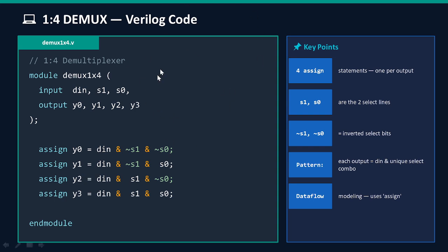After that we are going to write Verilog code. Just like for 1 is to 2, you create a design block using module, mentioning the input and output values. After that you assign, mention every output Boolean expression, and then end the module. This is the similar pattern for writing Verilog code.